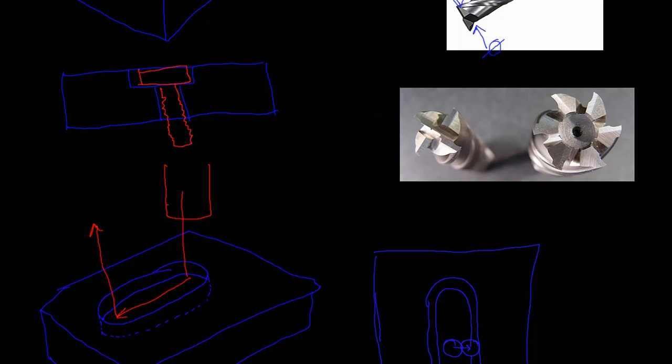So in this one, you see that this cutting edge is continuous across these 2 flutes, but discontinuous on these 2 flutes. So when this tool plunges into the material, just like it would over here, this is going to cut the material continuously. Whereas if you tried to plunge with this tool, you would break the tool, it would just explode, and the material would be damaged as well.